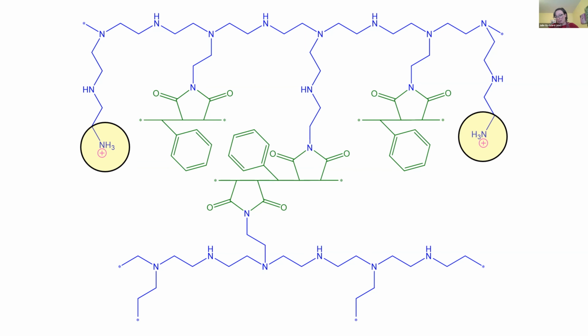But it brings a good question of, wouldn't these cationic groups actually promote fouling on a surface, right? A lot of the biological and food world is negatively charged. And what you don't want to do is make a positively charged surface to which there will be adhesion of proteins and things that essentially make a beautiful place to form a biofilm.